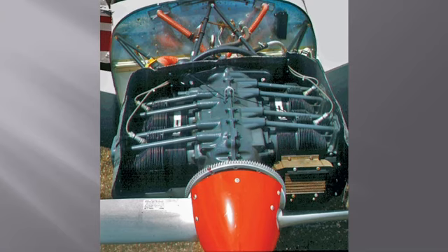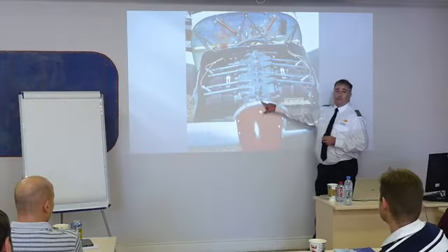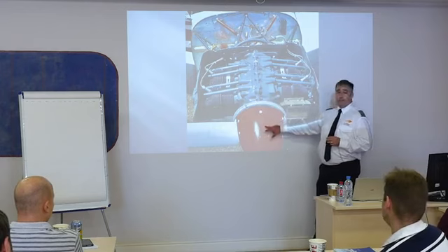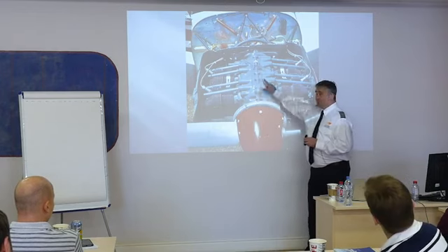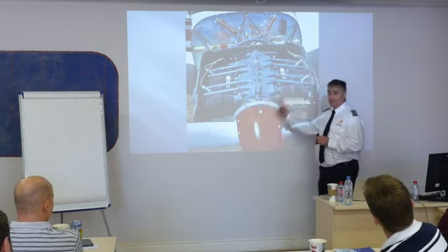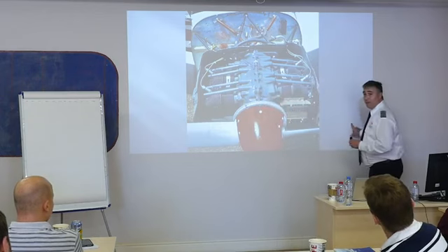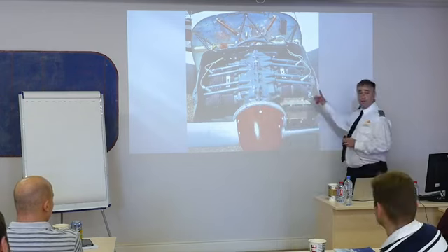You won't fly that airplane in the training program. Not for private pilot, not for instrument, not for single engine commercial. And in fact, you may not ever fly one of those engines with gear reduction until you get into turbine airplanes and turboprops, okay? Key point is that that crank is connected directly to this. If the crankshaft inside the engine turns around one full 360 degrees, that propeller turns all the way around 360 degrees.